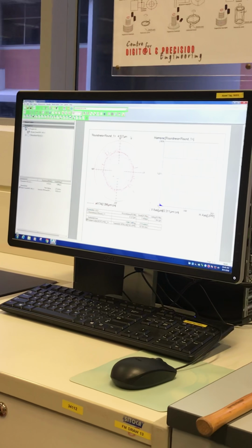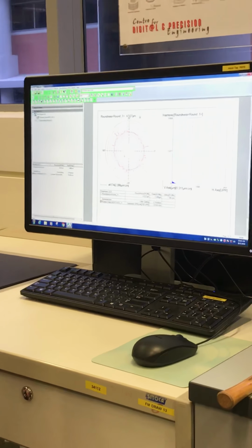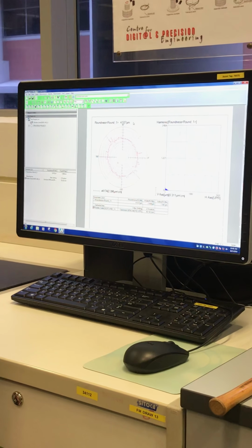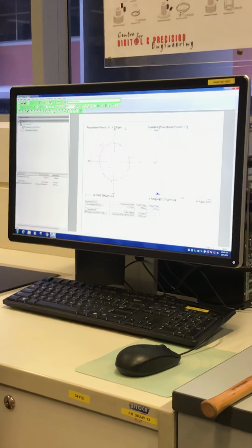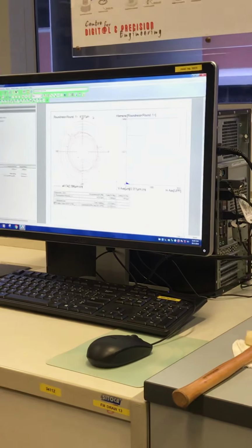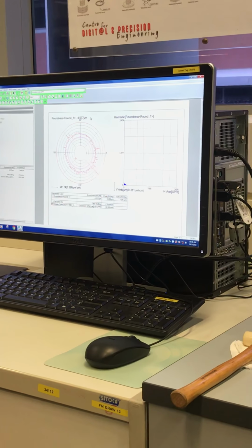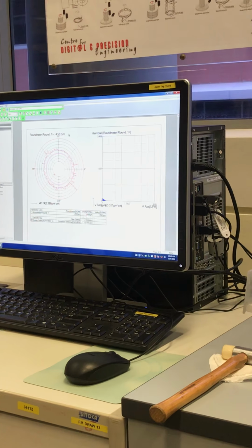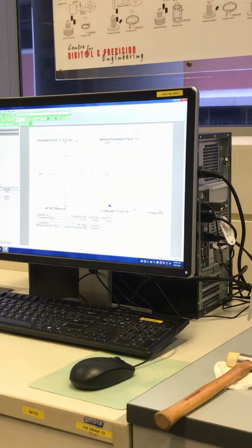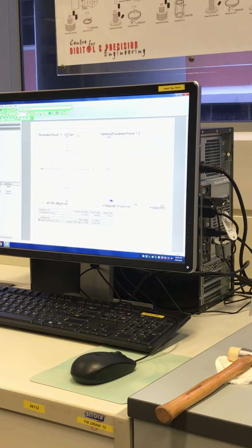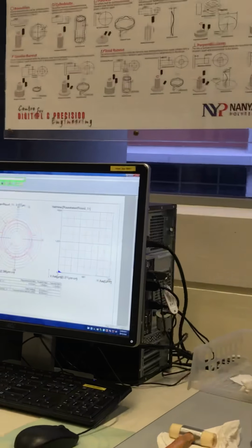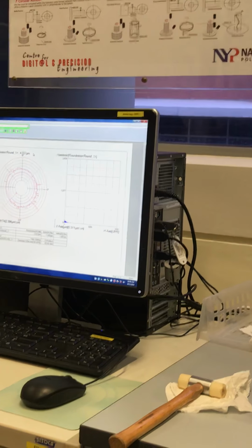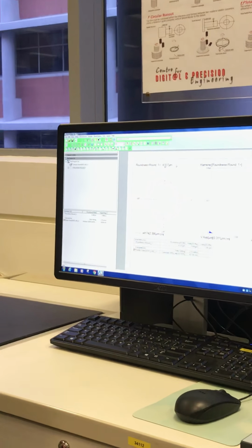This one, how many? What is the tolerance? How many micron? Tolerance, how many micron? 0.02. How many micron? In terms of micron? This is mm, right? 20. Drawing is always in millimeter. Micron, 20 micron. So 4.5 micron means it's in. Then any deviation?